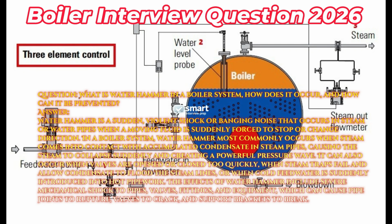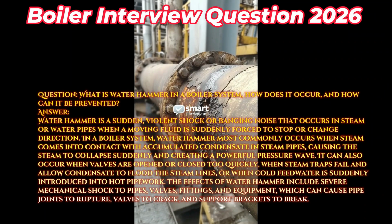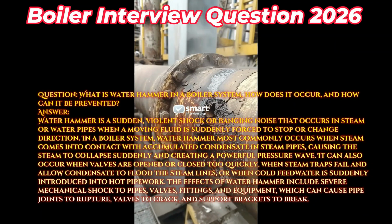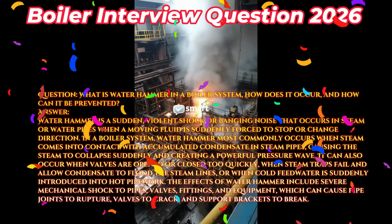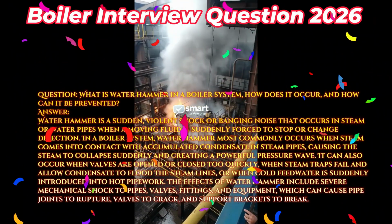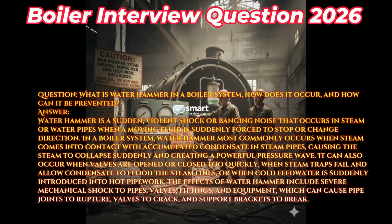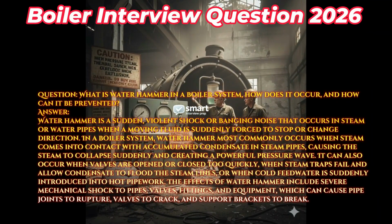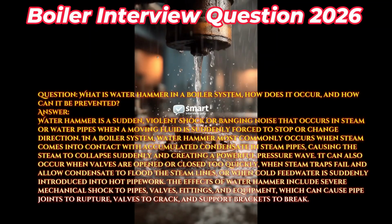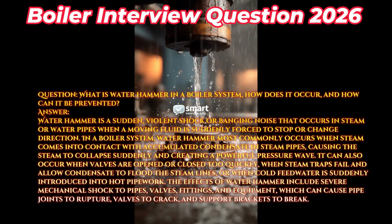In a boiler system, water hammer most commonly occurs when steam comes into contact with accumulated condensate in steam pipes, causing the steam to collapse suddenly and creating a powerful pressure wave. It can also occur when valves are opened or closed too quickly, when steam traps fail and allow condensate to flood the steam lines, or when cold feed water is suddenly introduced into hot pipework.